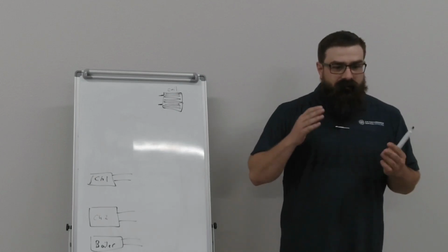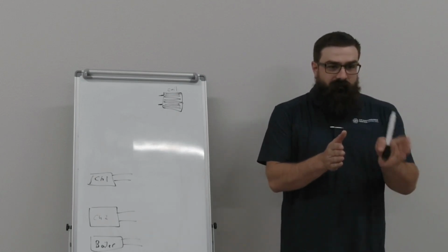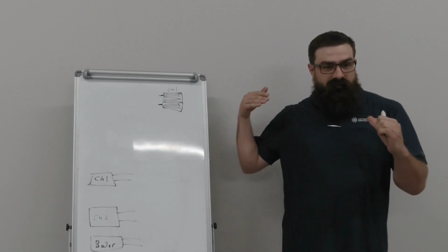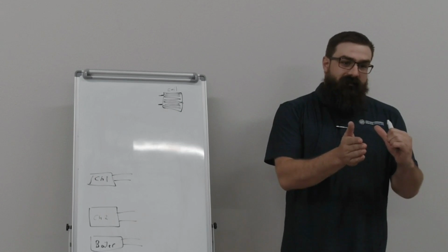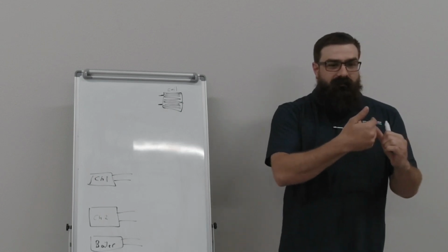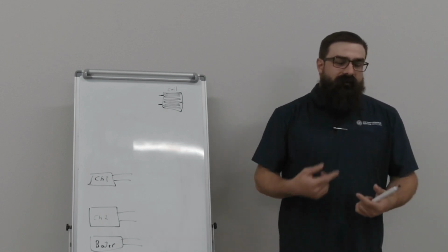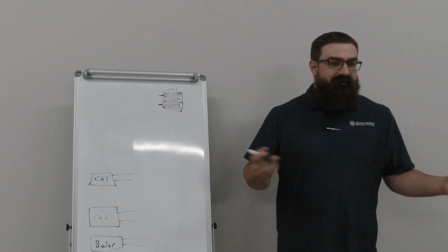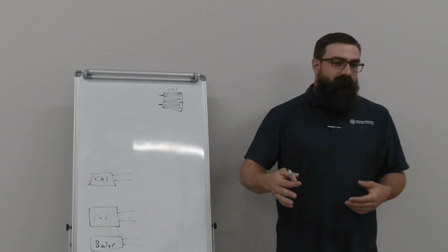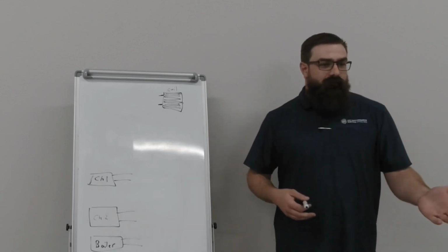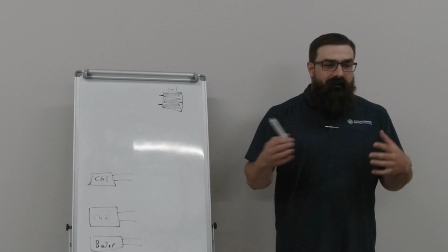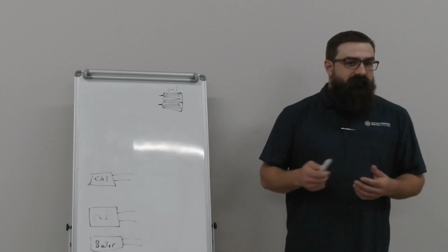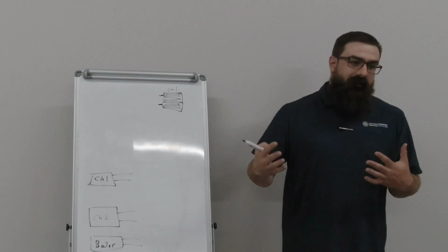Because to me, supply and return out of a cooling tower is: supply is the water going back to the chiller that's been conditioned. Return is the water coming from a chiller that needs to be conditioned. But then you go to the chiller and it can flip-flop. So we always like to refer to things as entering and leaving. It just makes it the easiest. So the entering water on the cooling tower, the entering water on the condenser, whatever it may be, entering and leaving is the easiest way to do stuff for us. So typically we like to just say leaving or entering.